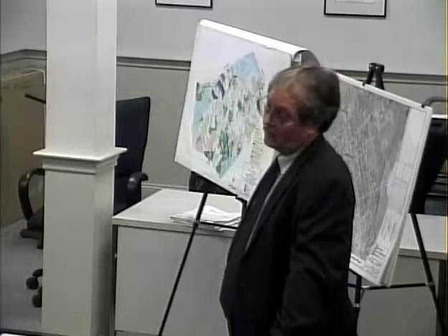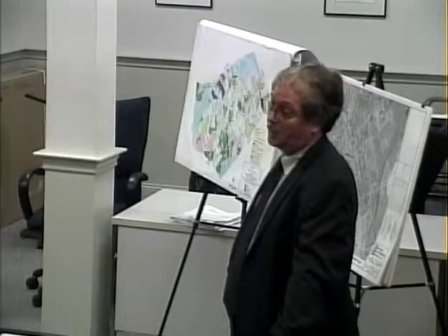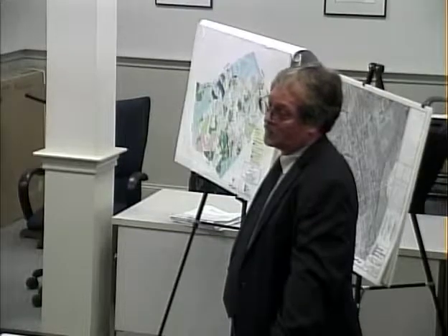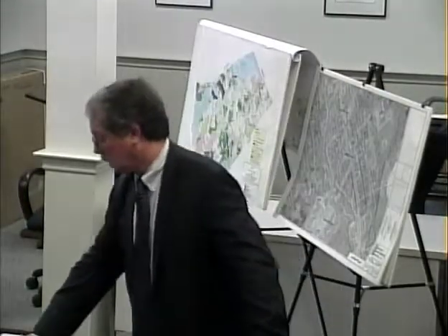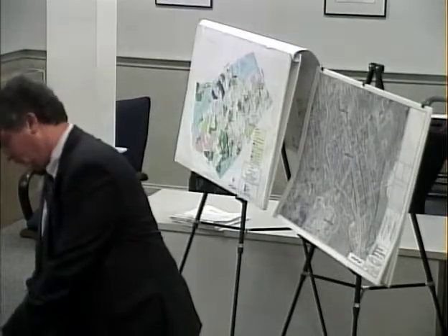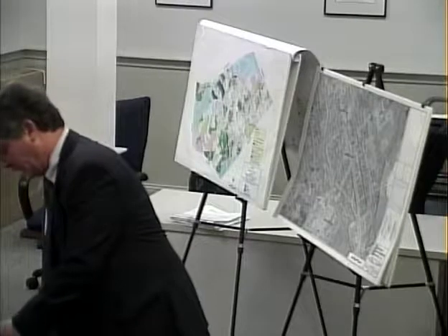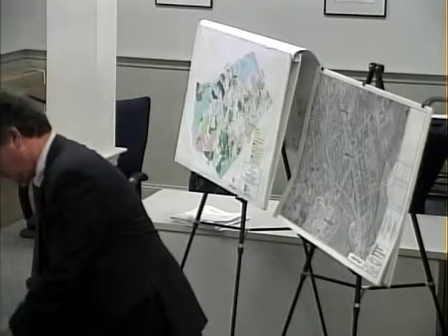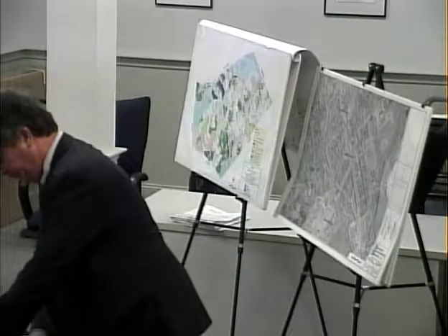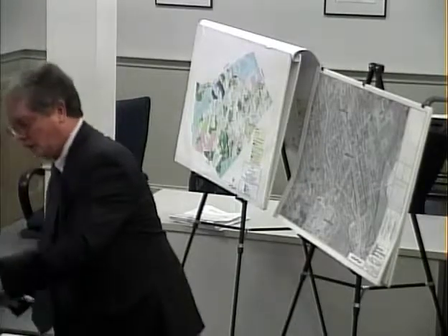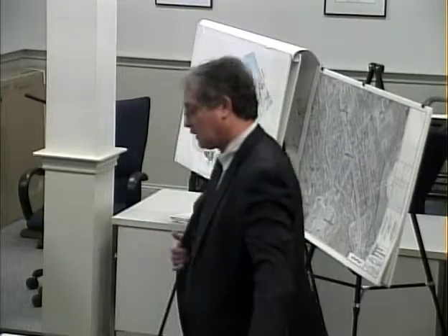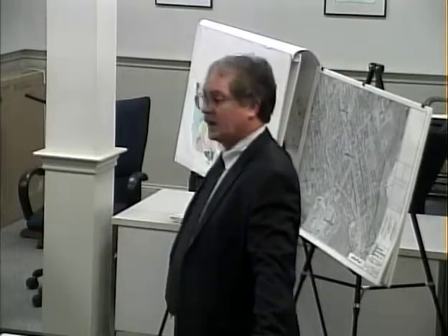When you design a system like that, you have to look at the velocities in the pipeline, so they are scouring. You have to look at the head losses, because it is a long pipeline as well. You can see some numbers I placed in the bottom of that first table, as far as peak flows or peak hour flows. Page 3, that bottom line, peak hour or max day flow: 40 gallons a minute, 90 gallons per minute.